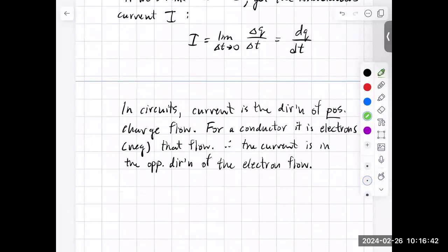Basically that's one of the things you're going to do in the lab. You'll have this long wire, you'll connect a power supply to it, and you will set a voltage, delta V. Then you will measure the resulting current using a little handheld multimeter set up to make current measurements. Then you'll take the same voltage and apply it to a different wire. In the lab, we're always using wire of the same material. If it's aluminum wire, we'll keep using aluminum over and over, with the same length of wire. We're just going to change the diameter of the wire, and see how the measurements change when we change the geometry of the wire.